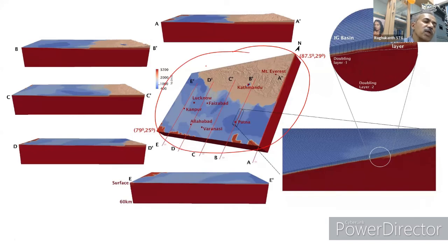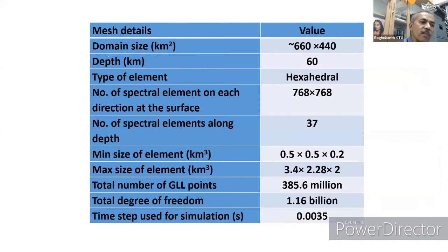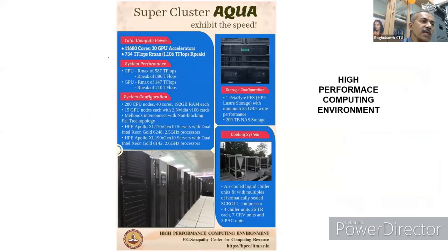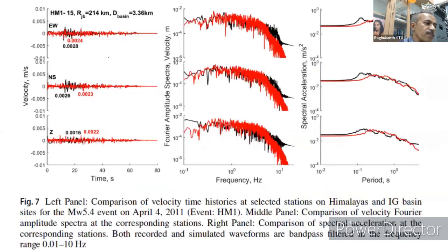As I already mentioned, this is my main primary area of research. To simulate these ground motions, we modeled the exact Kedarnath terrain in finite element, and we simulated a lot of time histories on the supercomputer available at our IIT. We got all these time histories for magnitudes 7, 7.5 and 8.5. So this is the ground vibration, the acceleration time history. This was then given as input to the temple finite element model, to see whether the temple will withstand or collapse, and what type of failure mechanisms you will see in the temple.